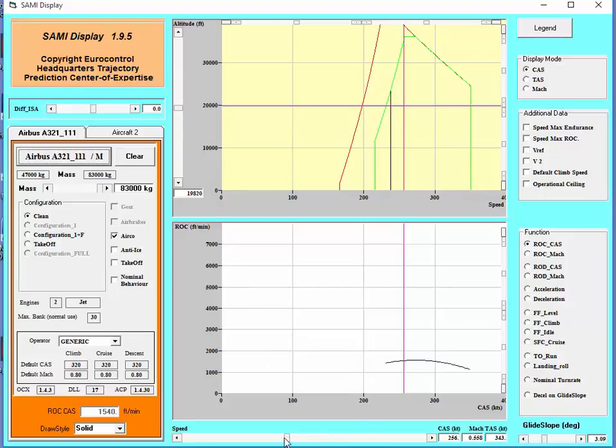At 20,000 feet, when we look at the various speeds within the operational flight envelope, you can read here what the rate of climb in feet per minute is at international standard atmosphere, in case that we have maximum climb power and the aircraft is maintaining a constant calibrated airspeed. Calibrated airspeed can be read off here. 270 knots, for instance, then you have a rate of climb of 1,559 feet per minute.